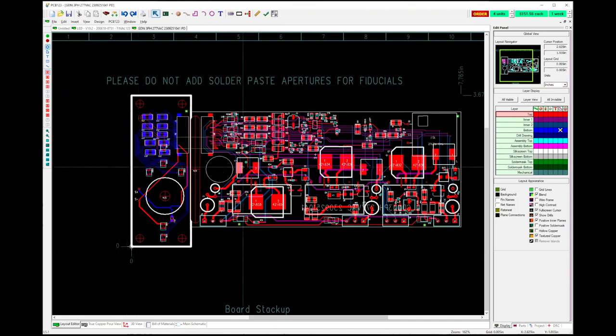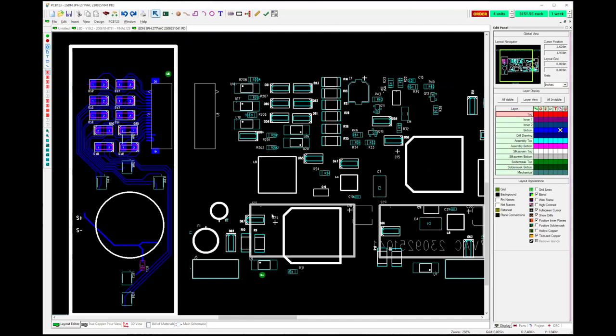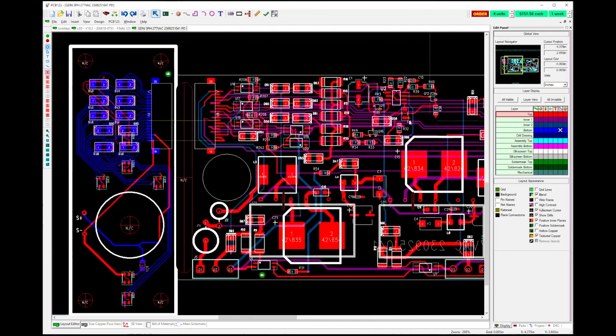One thing that I do when I route the board, using the signal routing, is I always set up with a grid that's fine enough that I can do a nice job of routing, but not so fine that I can't ever hit anything. For example, if I want to route two things together, I found that a 5 mil grid is pretty useful in routing stuff like this, because I can always come out of a pin that's not on a 5 mil grid, take my trace up to a grid point, and then route everything on a 5 mil grid. It comes out looking a lot nicer.